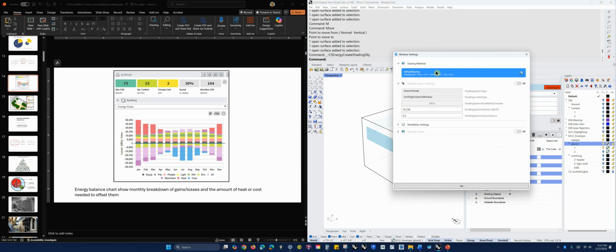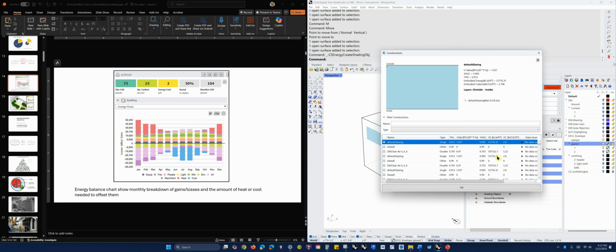If I edit, I can come to this default glazing. And we've talked about glazing before, so you could choose, for example, a lower solar heat gain coefficient. You could choose a really low U value. If you click on the columns, it organizes them in number order. So I can come and find very low U value configurations.